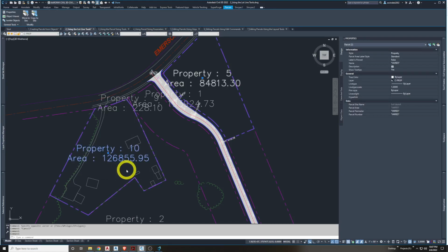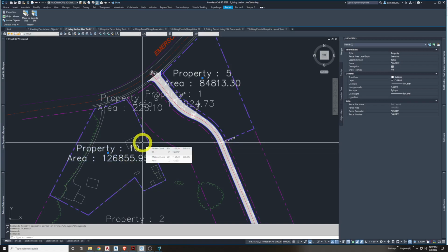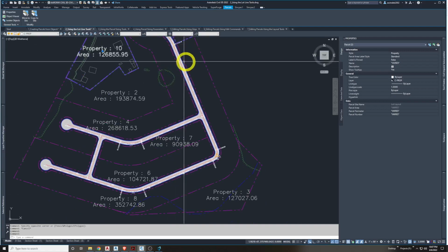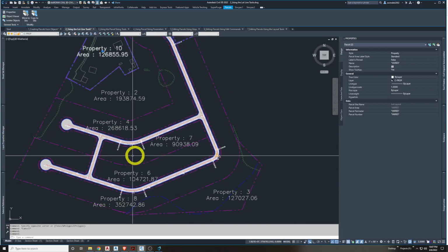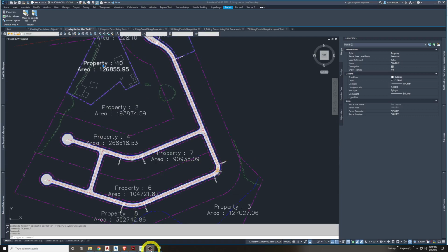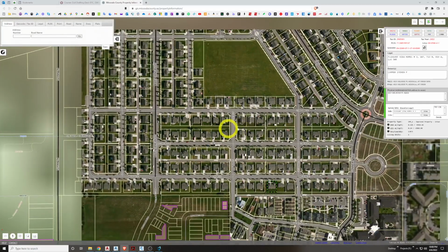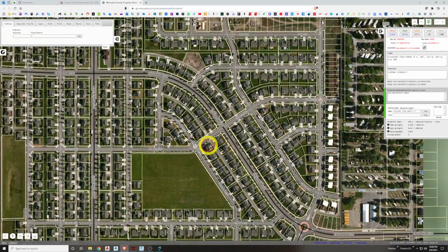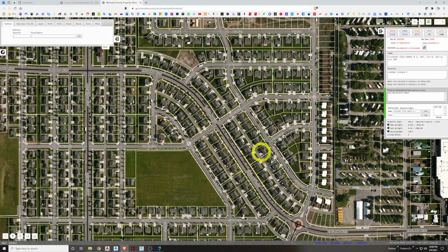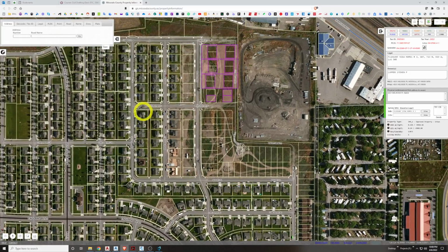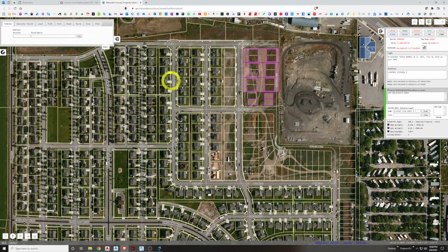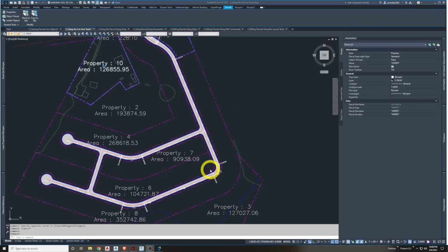So let's skip to the next area, 12.3, which gets a little more into the parcel sizing tools, which are by far the more powerful things to use here. They basically help us optimize little parcel layouts inside of these little geometries, as we see somewhat in maybe a city layout here. We might help optimize these in a whole block area, or maybe along a curve here. We're going to optimize them into fitting a certain basic geometry with certain constraints, widths, various things. So we're going to get into that on page 2-39.